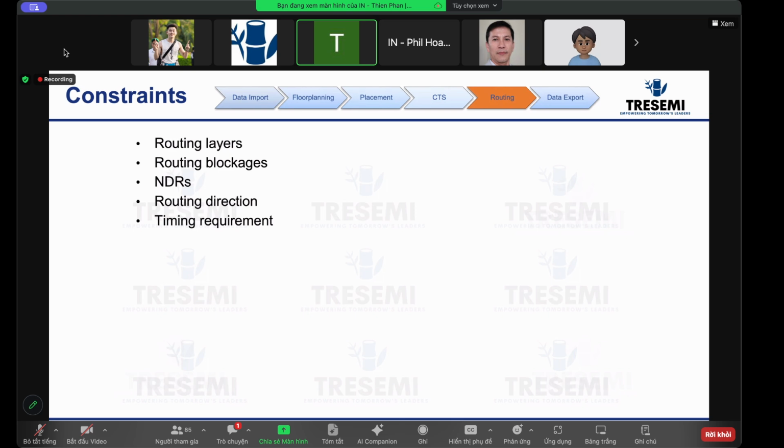So if you look at the chip, whenever we have macros, we can't route through the macro. So usually we can only route over, and sometimes you can't even route over, right? If the memory uses up all the available layers, then you can't route over. You have to go around it. So that's the constraint to the router, right?